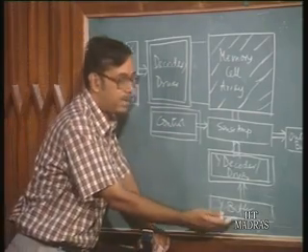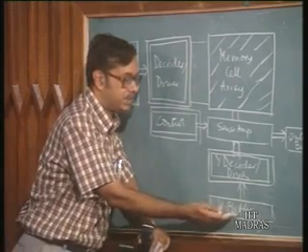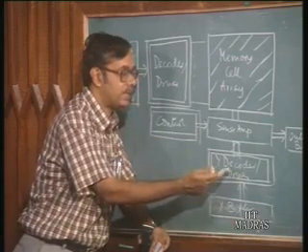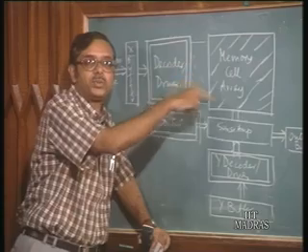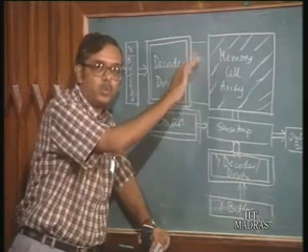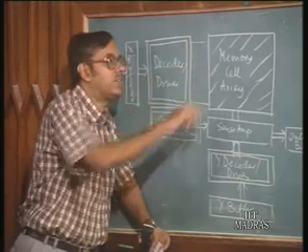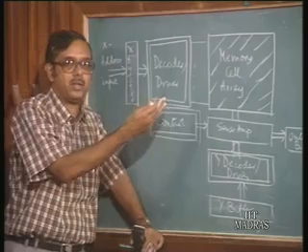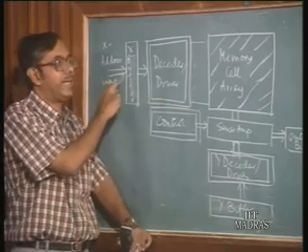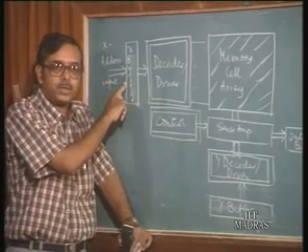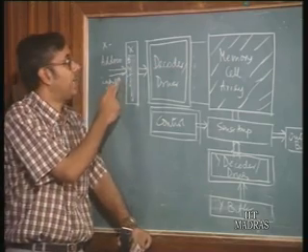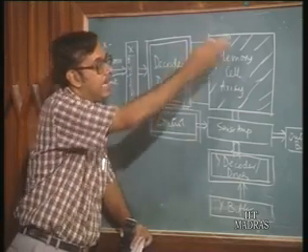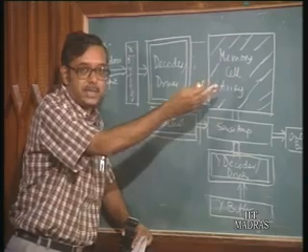So, you require buffers to convert these levels into the standard CMOS levels, because you see the memory cell array is actually using CMOS. So, it has to be converted to CMOS levels. So, in fact, here you have negative voltages. Okay, ECL level is negative voltage, and this has to be converted, and this has to work in a CMOS environment inside.